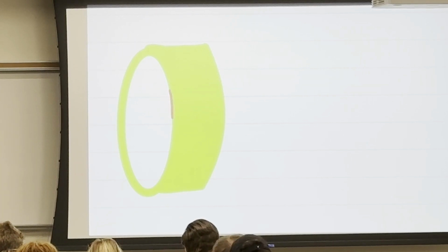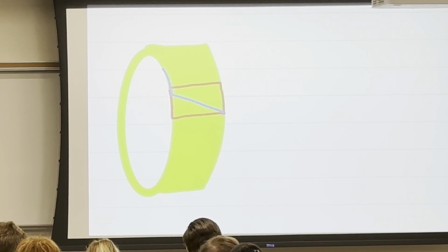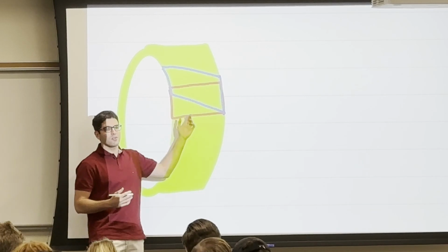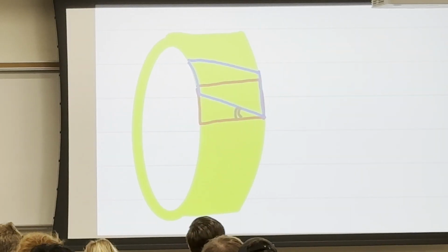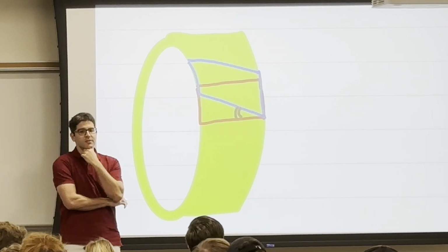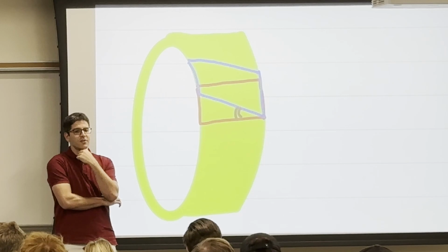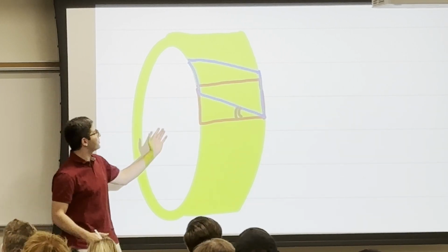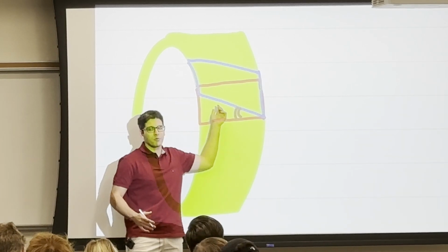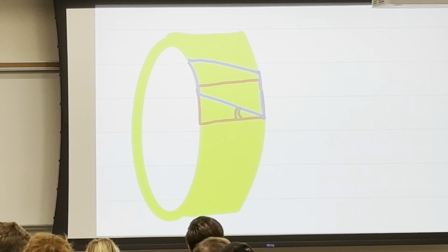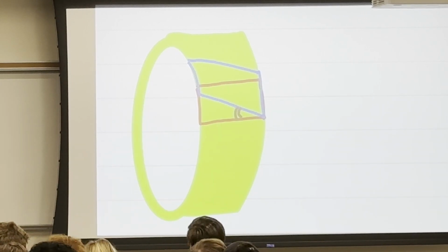So originally, this was something like this, right? And when I applied torsion, it went like this. Do you agree with me? Okay. What does this remind you of? Or in other words, what was this angle from the previous lectures that we discussed? What's that? That's correct. So this is a shearing stress that's happening here, and then within the shear stress, what was this angle? What we used to call it? Anyone? It's what? That's correct. That's a shear strain. Do you all see it?